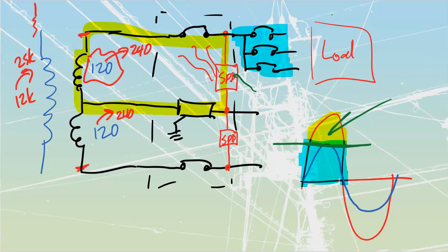Elevators can sometimes go into overdrive, right? If your elevator is accelerating downward, it can overspeed the motor, and that can act as a generator on the system, raising the voltage. We also have some loads that in and of themselves have massive amounts of surge inside, where they're literally moving fluids. Air is a fluid, so is gas. So blowers and air conditioning systems are all going to have that.